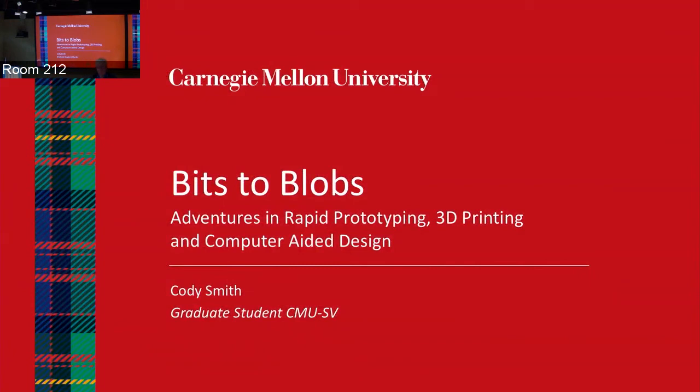At some point, your extruder becomes the limit on how fast you can push the material through, especially when you're doing something really imprecise. Like there's this extruder called the E3D Volcano. It's huge, and it can print very inaccurate but large things quickly. And it turns out that keeping that thing sufficiently fed is a challenge. And that goes back to the concrete printer. You don't really care how precise it is. Your speed would be the dominating factor there. And that goes back to the constraints we talked about, where if you pull on one, you're going to lose others. So speed usually means an accuracy trade-off.